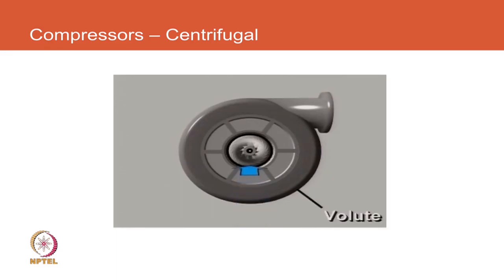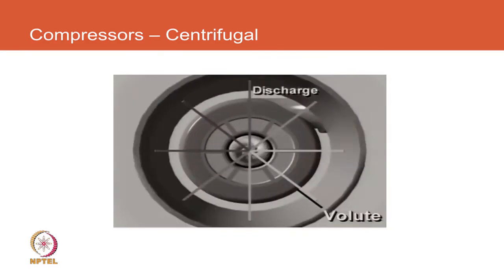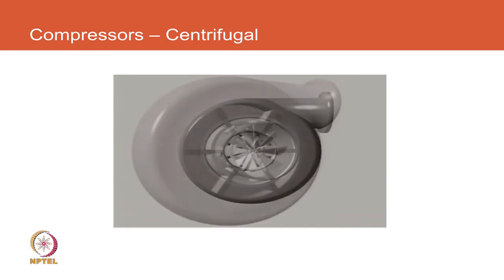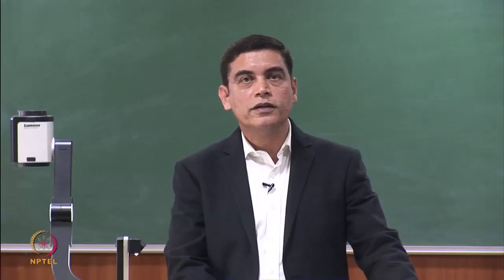And then we need a means of capacity regulation. So to regulate capacity, we use something like a blocking device at the inlet of the centrifugal compressor. So those guide vanes would close partially in response to needs for capacity changes. So here you can see them gradually close when part load capacity is required and open fully when you need.